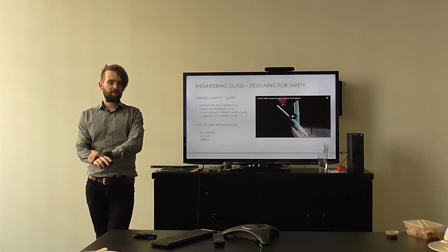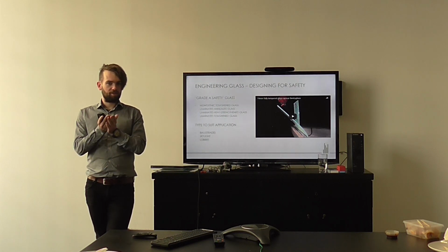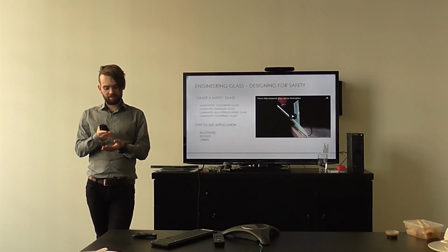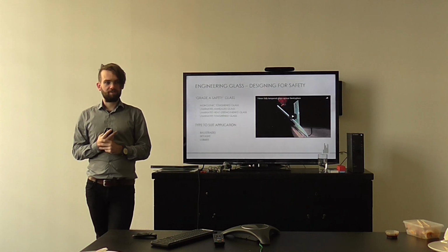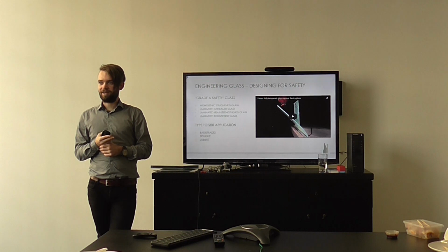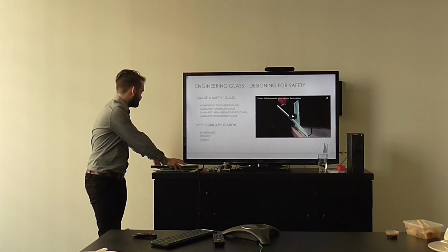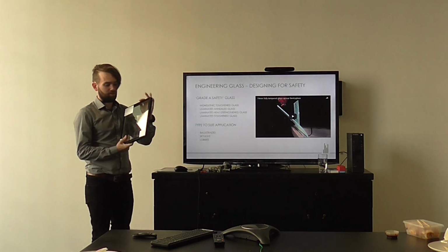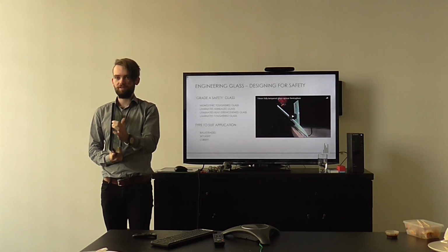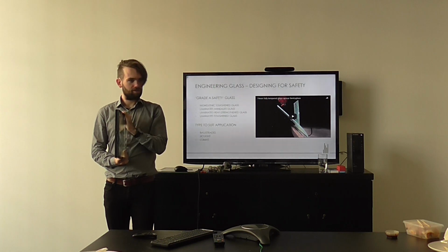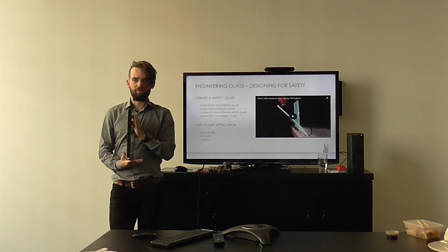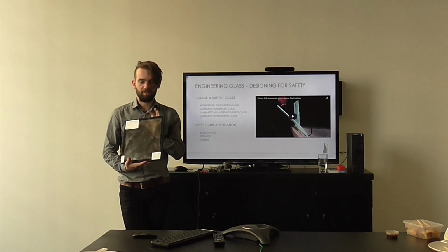One of the key points touched on here is that it's very important that in an insulated glass unit, or even in a laminated glass unit, the block sits under both lights of glass. It can be very common to see on site that they might push it to the back, and you've got one light of your IGU sitting on your block and the other one not. Eventually you're putting strain and stress into the silicone which holds the two units together, which over time can lead to the deterioration of the insulated glass unit.